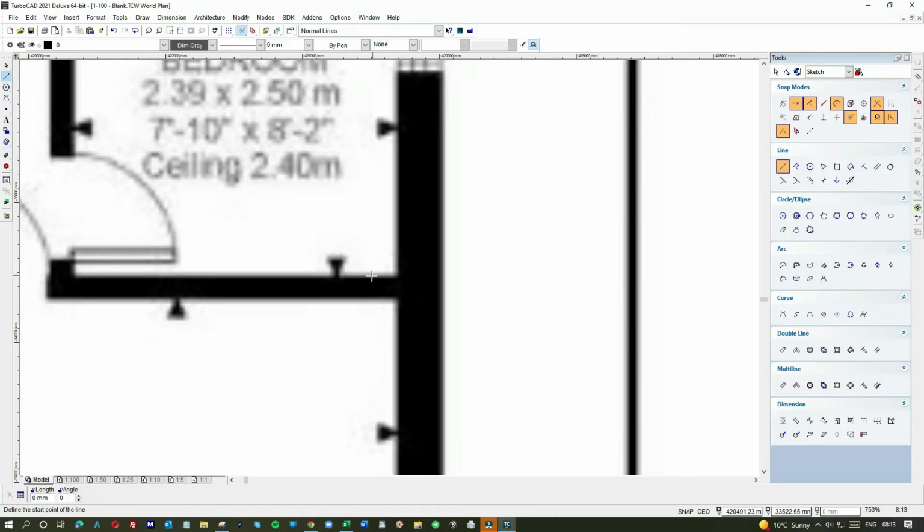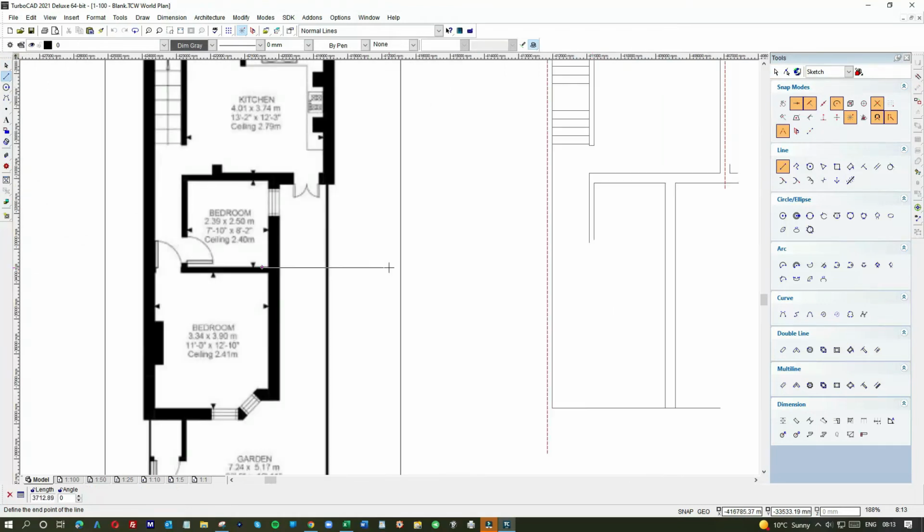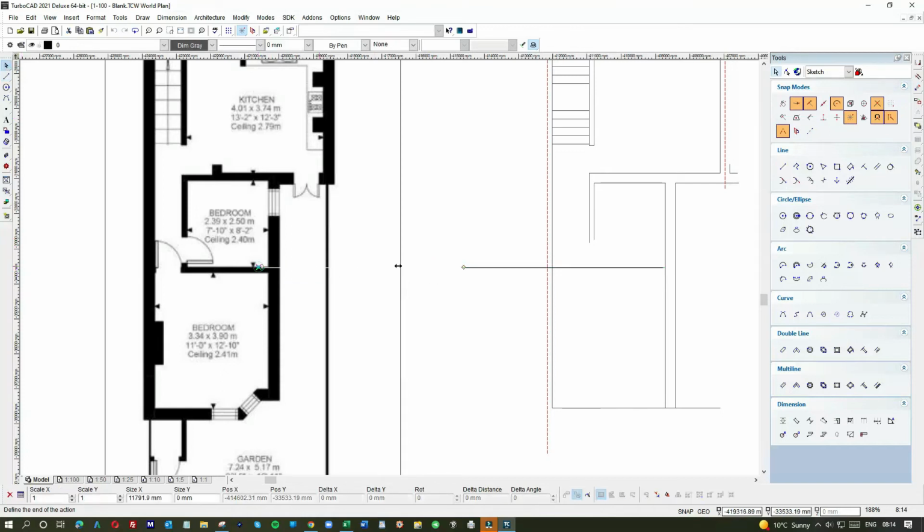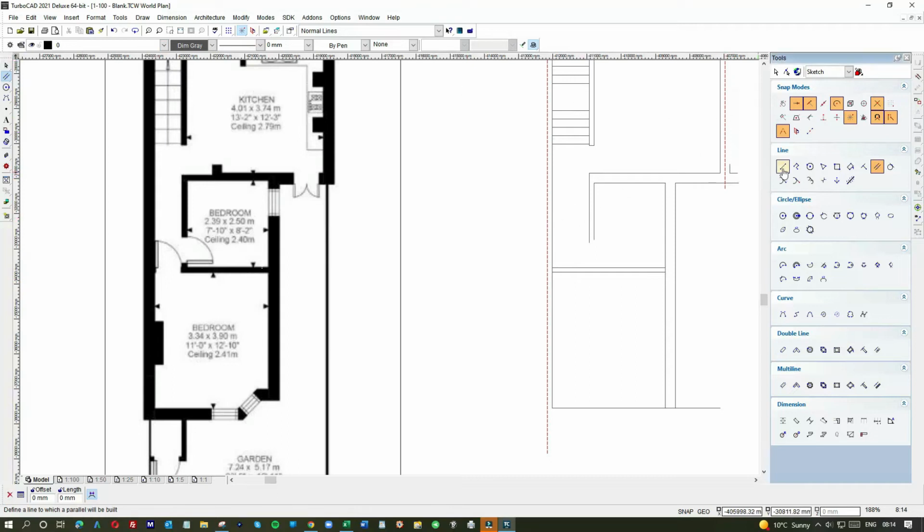Right, so now this one, partition wall. Again, it's most likely modern, because that's not necessarily how the layout would have been in the old days. So being a modern partition wall, it's 100mm of stud work, 12mm plasterboard on either side, and a little bit of plaster. So we allow 130, and 130 would be quite accurate. Tab 130. Right, let's link it up.